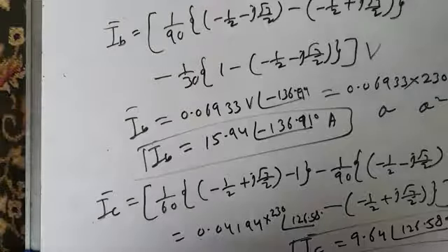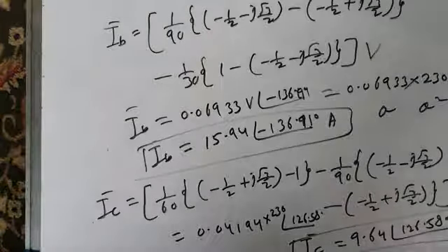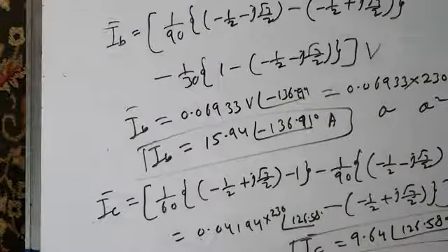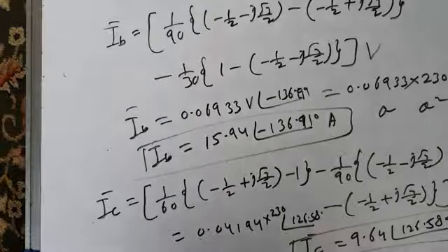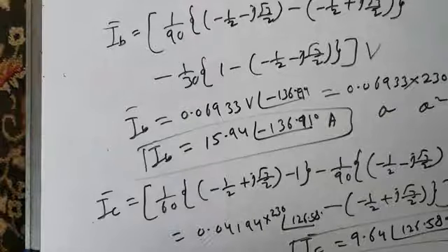Another inference was that if the system is three-phase, three-wire system, neutral wire is not provided, then VNN is not equal to 0, but the phasor sum of 3 line currents IA plus IB plus IC is 0. And last inference was that if it is a three-phase, four-wire system, then whether your system is balanced or unbalanced, neutral to neutral voltage VNN is equal to 0, but the phasor sum of 3 line currents IA plus IB plus IC is not 0, that is equal to neutral current IN, and that is of course equal to 0 sequence current. Then we took a numerical problem and solved it.